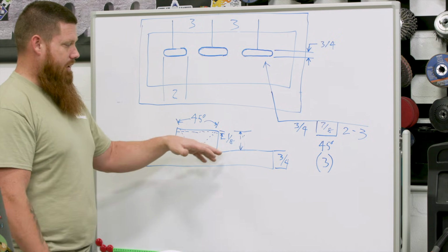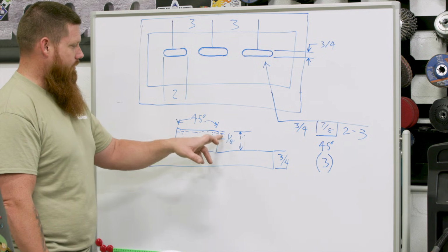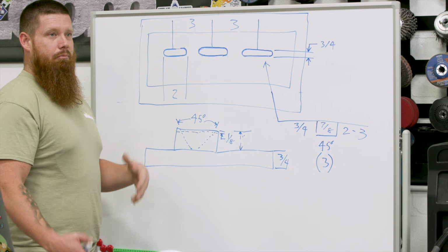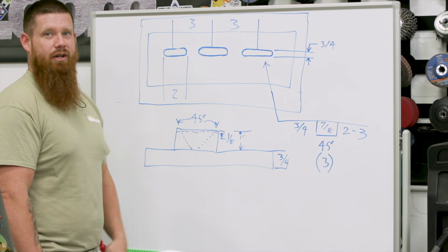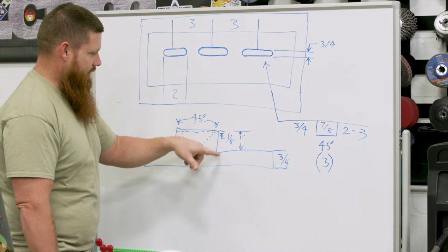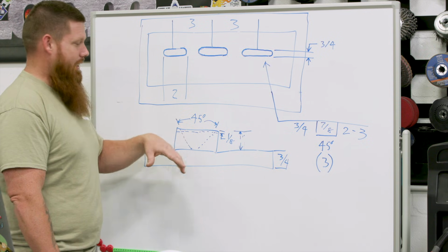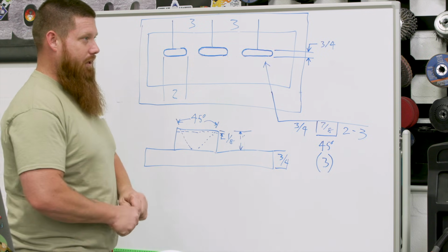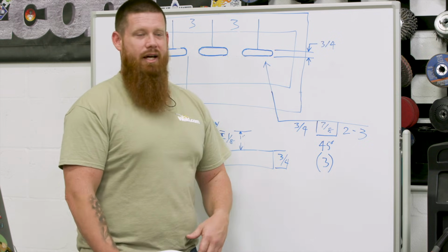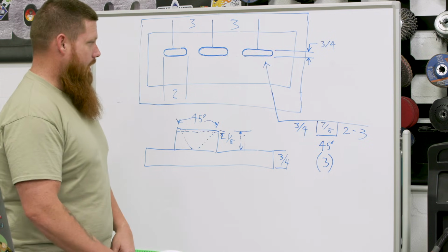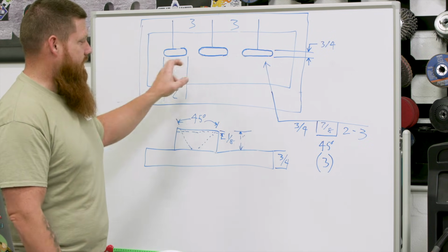Again, this could be a lap joint or regular T-joint where you could put a fillet weld in here, but there may be other intersecting parts where that weld's going to interfere. So instead of beveling the plate that's going to lay in here, we'll just weld the inside of that and we don't have to worry about it. So a lot of bucket blades, you're going to have slot welds or plug welds on that. If you have to repair those, there's a bunch of different instances where these would take place.